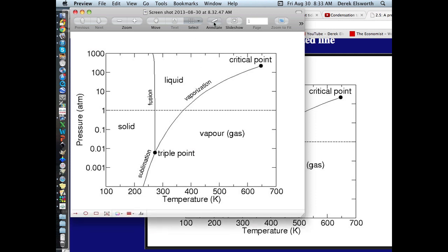So vapor pressure, of course, is the idea that you can boil something by changing either the temperature or the ambient pressure at which it lives. Fluids with a free surface always have an exchange of molecules across it. If you net lose the liquid to the air, then you're evaporating.